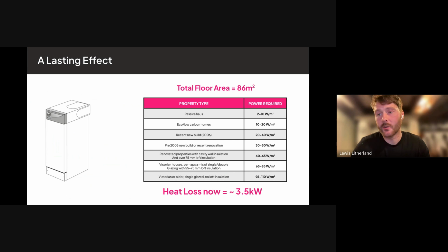100%, mate. Brilliant. So these older houses, as he says, they're mostly oversized. The rads are oversized. The pipework's oversized for a condensing boiler. But for a heat pump, that's great for us. The fact that I was so bad at doing this means that when I fit a heat pump, it's nice and easy for me. The rads are already huge. I just didn't touch them. They were already sized for when the heat loss was massive. I didn't go out and start changing pipework when they changed from single glaze to double glaze. So it's already oversized.